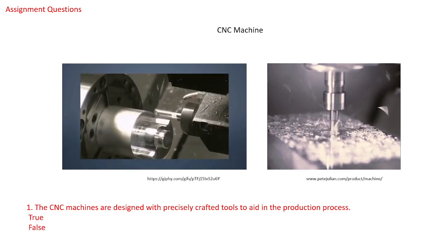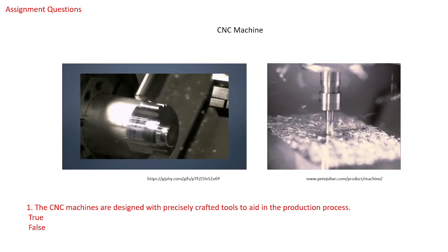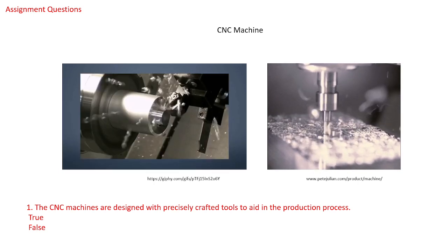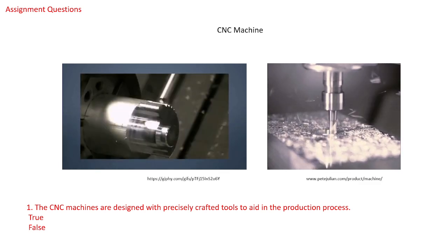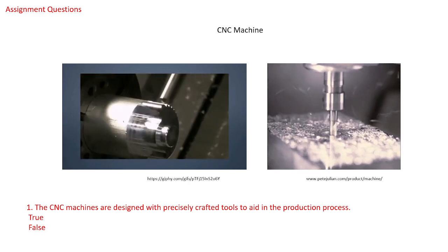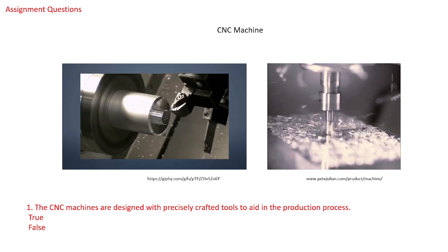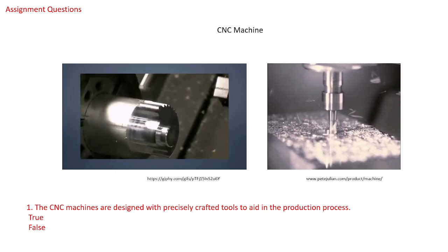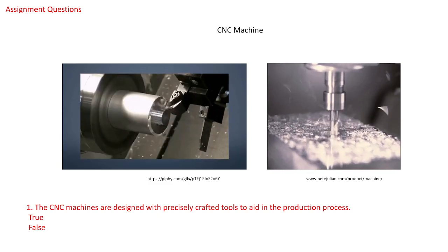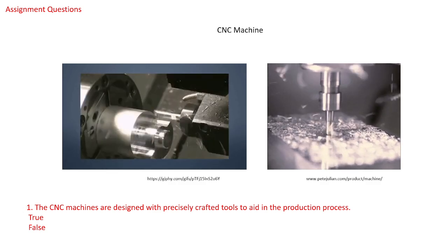The process is very versatile in nature, and it's compatible with various materials, starting from aluminium to plastics, wood or glass. The milled parts have high tolerances, as milling machines can achieve a tolerance between plus minus 0.001 to plus minus 0.005 inch.